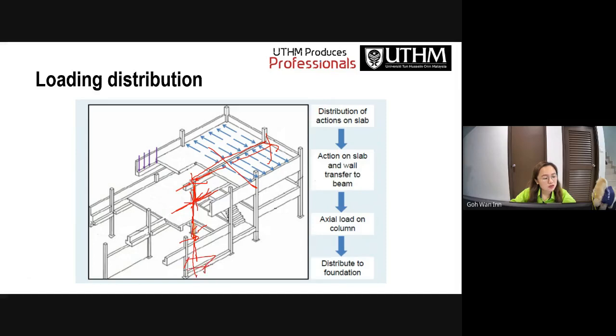The foundation normally sits on the hard rock area. That's why you have the piling, right? Like for the Batu Pahat area, we are on peat soil, so normally all the buildings have piling. The piling will be set until the set area, which is the hard rock area, to sustain the load from the building.